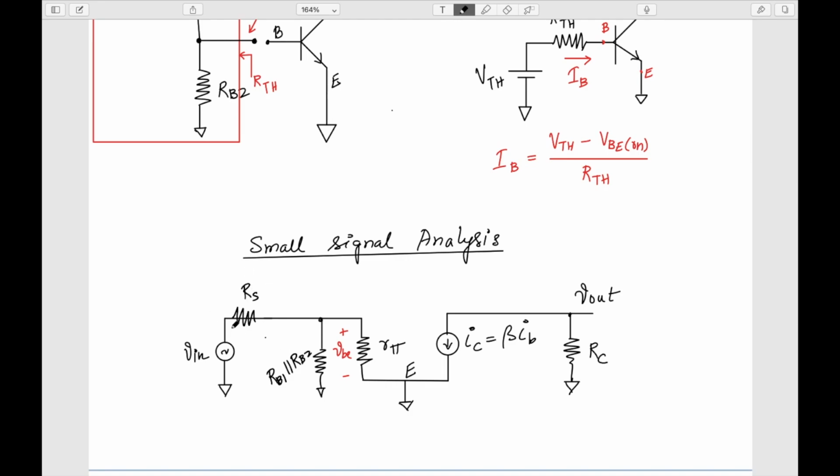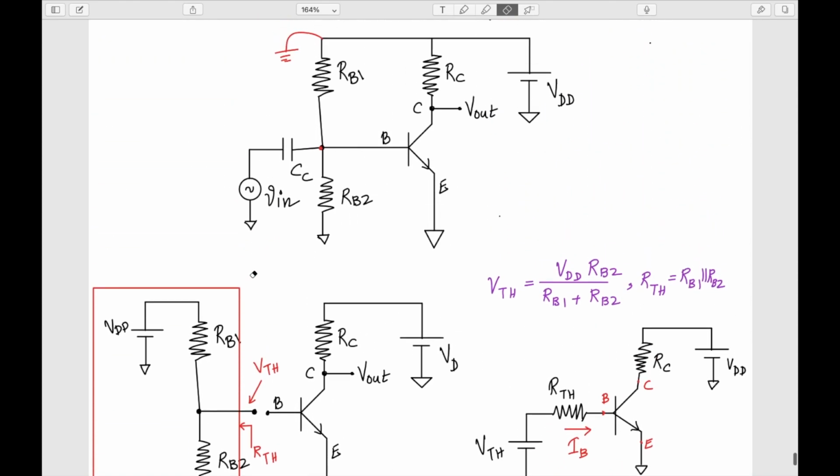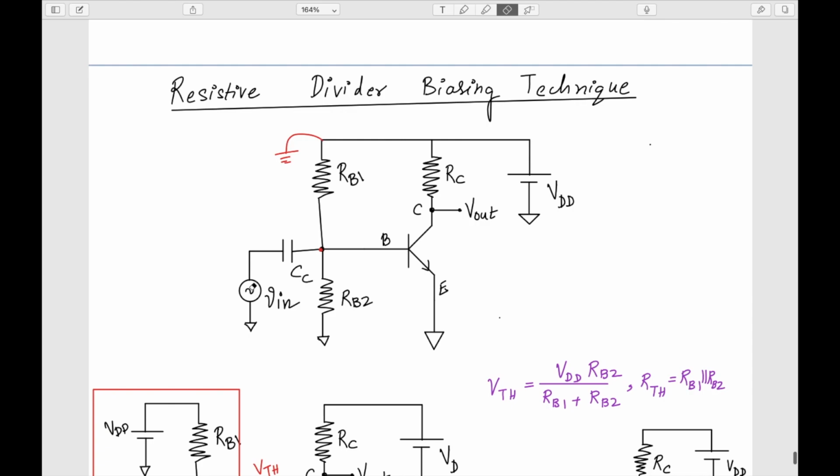So of course this is important. Till now we have been considering a source without resistance, but in a real-life case, any source we consider, any sensor like a microphone, also has a resistance. Right now I am speaking into a microphone and the voice is getting recorded. Any sensor or voltage source, any signal that we want to amplify, will have a resistance Rs in series, and this resistance comes into the picture when I write the gain expression.